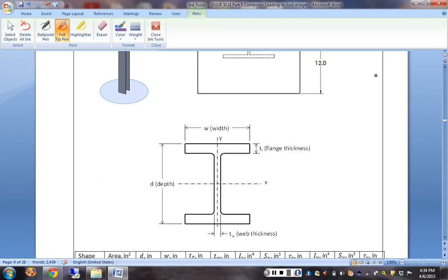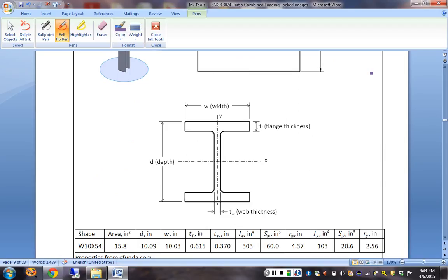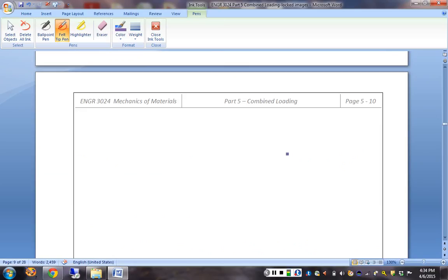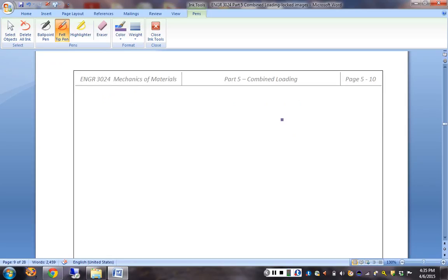So we've seen the beam tables before, where it gives various parameters. It gives distance, and it gives the moment of inertia about either axis. So all of these are quantities that we're going to need. We know that this is a cantilever, so we know that the worst case scenario is going to be back at the connection point at the base. Like if we took a hacksaw and cut it off right at the concrete where it's connected, that's where our worst case will be.